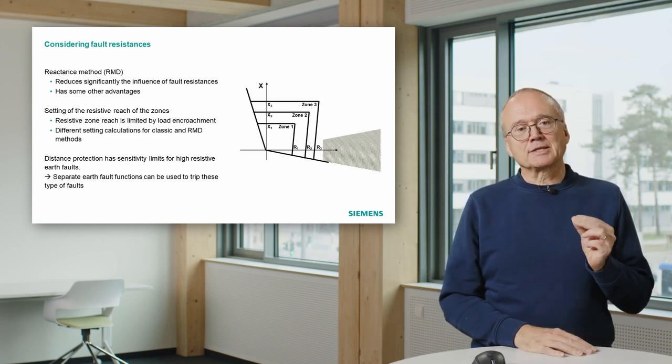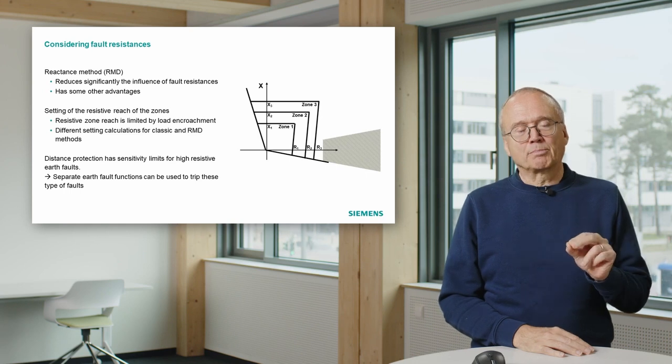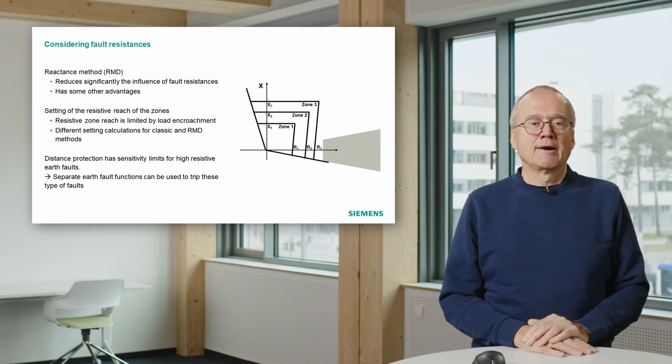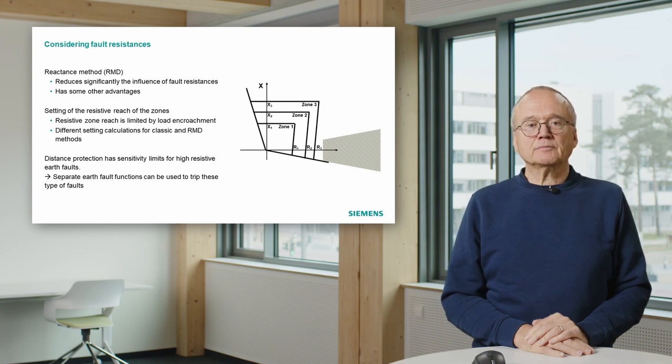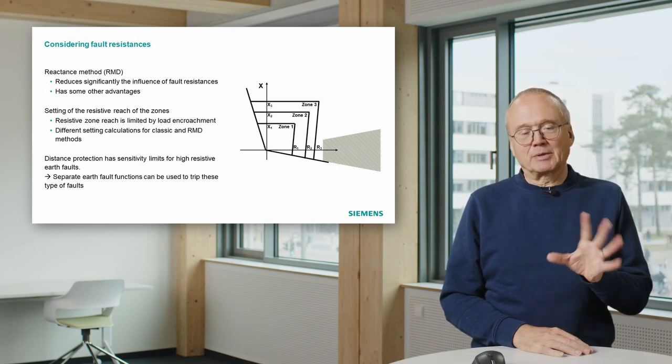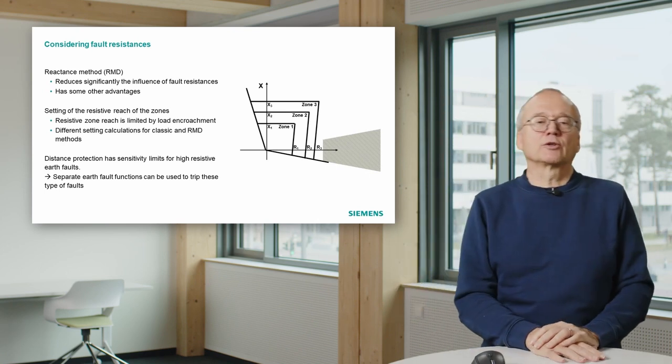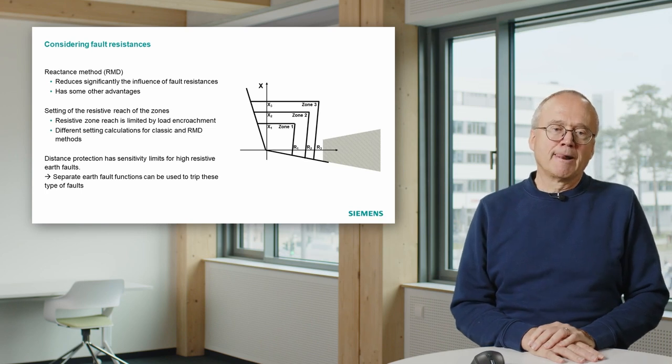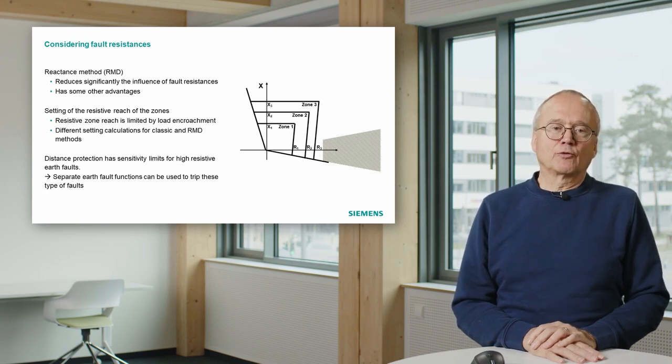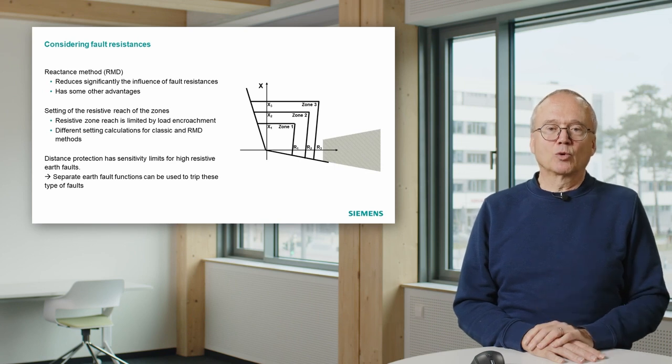And important is that you do proper setting calculations for the resistive reach. They are sometimes different, especially if you look into single phase to ground faults. They are different for the classical method and the RMD method. So please have a look into our setting examples in the manuals.